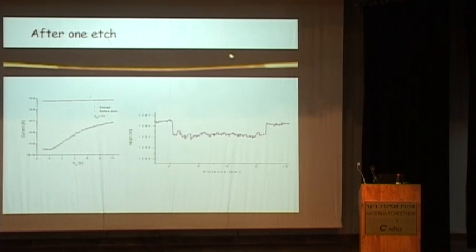Some people have done it like this, after growth. There was a paper even in Nature Nanotechnology, but they also found a very inhomogeneous dopant profile. You're right, but the issue is that you have to grow the wire at the gold-silicon eutectic temperature of 500 degrees C, and this is the most common method. The object of our work was to find what the diffusion gradient is.